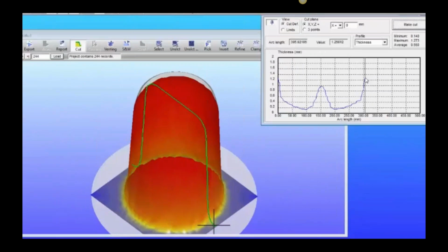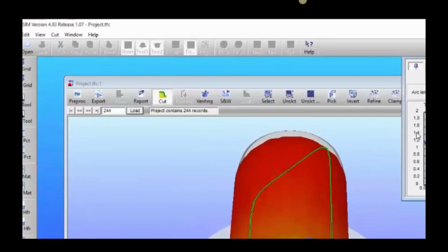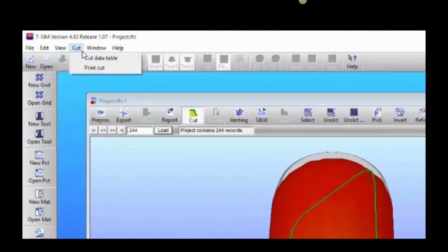And you'll see the graph is linked to the graphics window, the crosshairs of the position is shown. Here we switch to the Y, and you can see symmetry will make it virtually identical result, either X or Y, and this justifies using symmetry for the simulation.